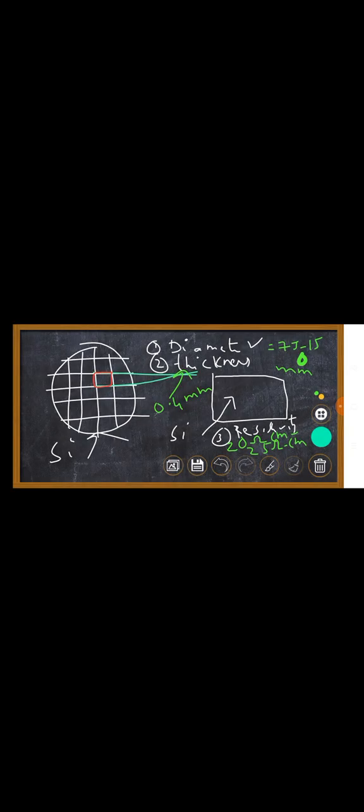Which type of MOS transistor would we like to fabricate? Absolutely, NMOS. Therefore, remember the substrate must be a p-type substrate. That means after creating a substrate, we have to dope some p-type impurities into this substrate. Therefore, we should focus on the doping concentration. Is it clear? This is the fourth specification you have to remember.